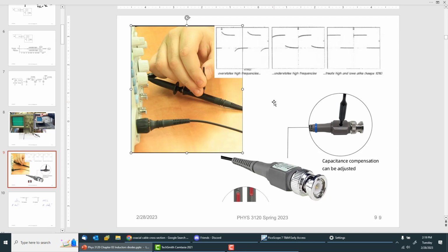I better learn how. So what you do is you connect your scope probe, set it to times 10, and connect it to that output. It should be a 1 kilohertz square wave. And you twist that screw until you get a beautiful looking square wave. So let's all do that. I'm going to pause the recording. And in fact, it's already 20 minutes long. I'm going to stop it and I'll restart a new recording.